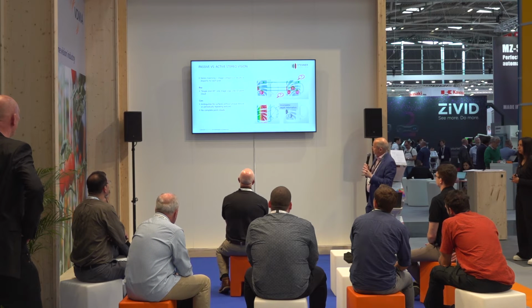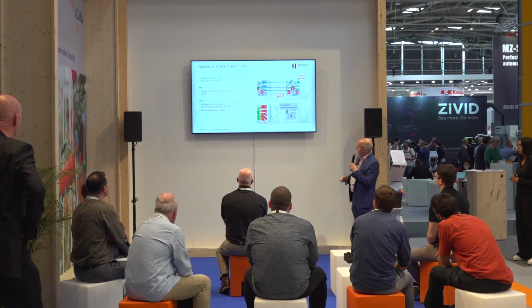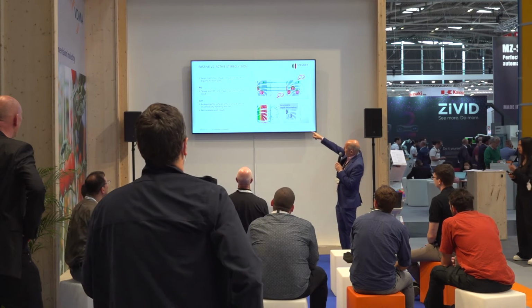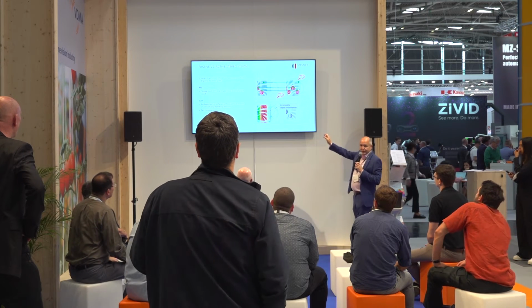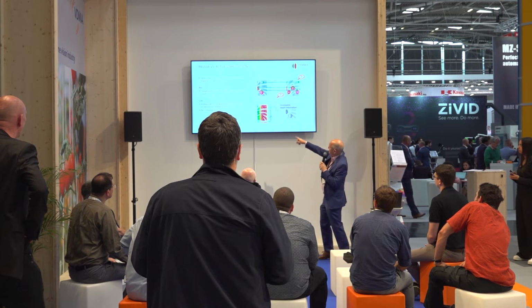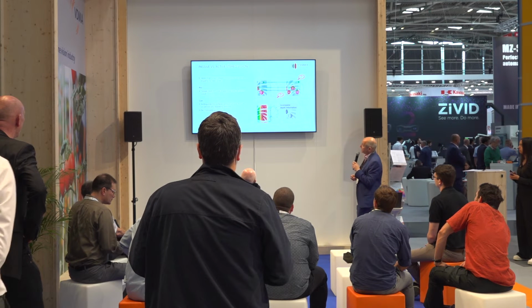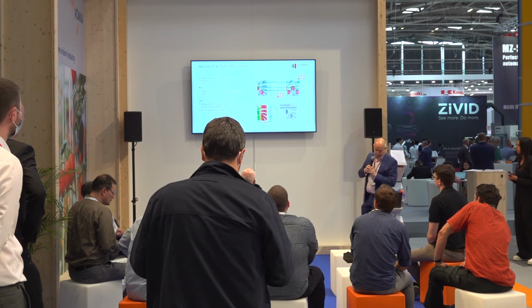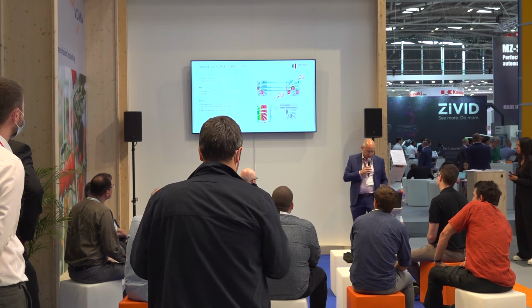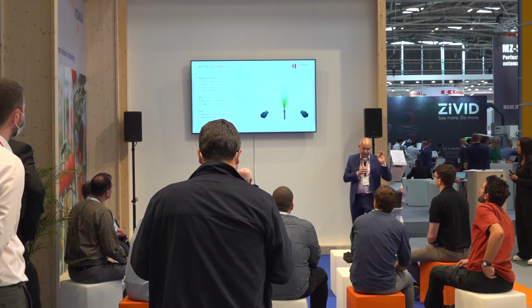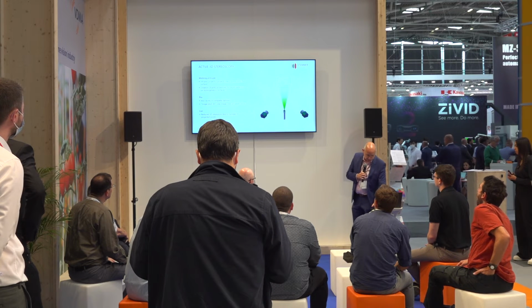But if there is a pattern or detail, you can. So again, if we're looking at, let's say, this mug, we would get where the edges are, we would get 3D data, but we wouldn't get 3D data around the white parts of the mug. So ambiguous surfaces without texture don't work. So you don't get complete point clouds. You don't get 3D data on every pixel if you need to have texture.